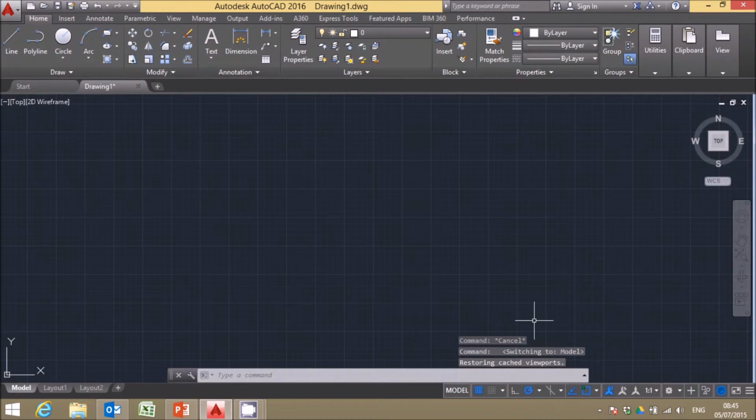Okay. Moving along, I have the option for grid, and if I just click on there, you'll see how the grid turns on and off. Next one, I have my snap mode, and this is specifically snap to grid, and you'll notice that that's in this section here. So this is my snapping to the grid.